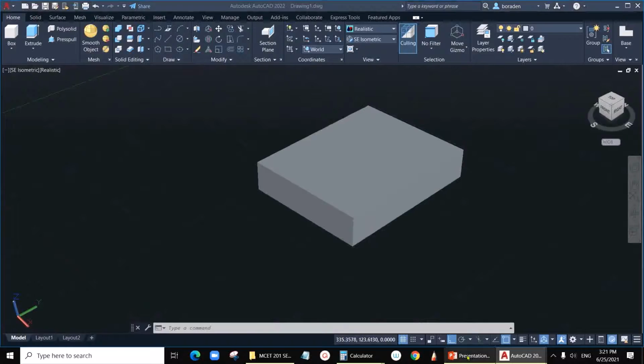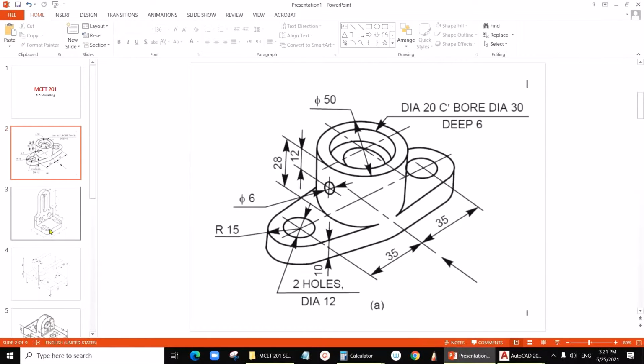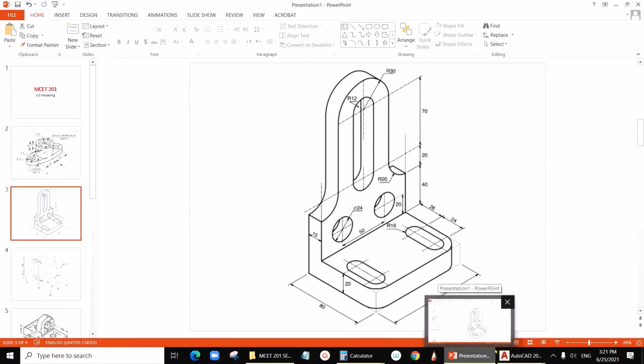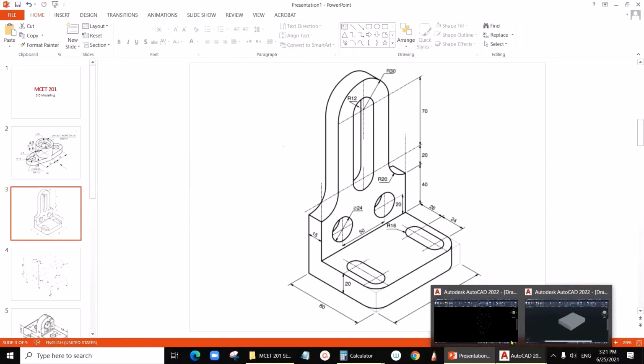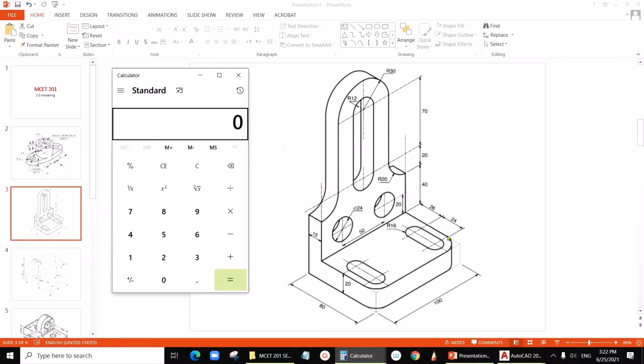Fine. Now here there is some fillet. Radius of this is 16. Okay, radius 16, I guess radius 8. Okay, this is radius 8. It is not 16. Okay, yeah, radius for the outside one, this distance is 80 minus, let's understand this. I want to get for this fillet this distance. So this is 80 minus this one, first 15, minus this 26, minus 24, this is remaining. So this radius here is 15.